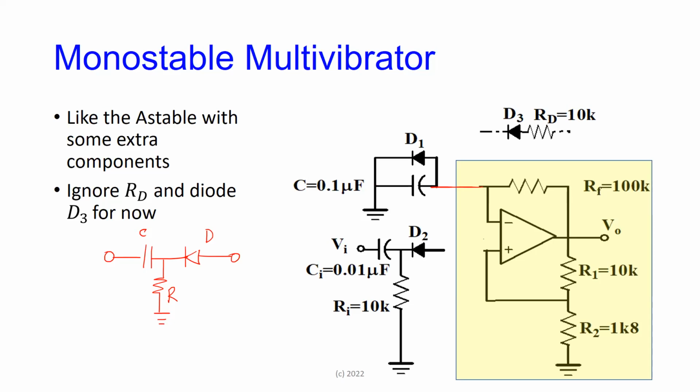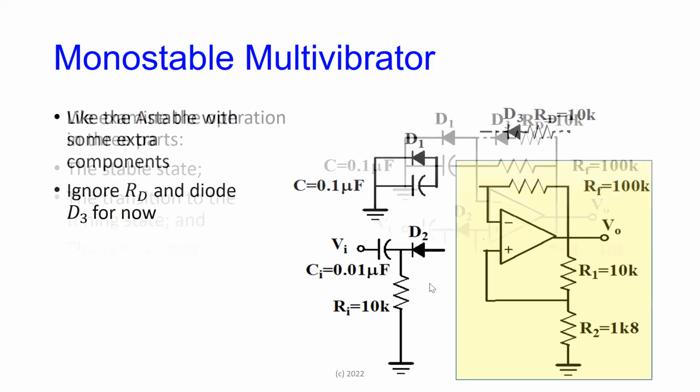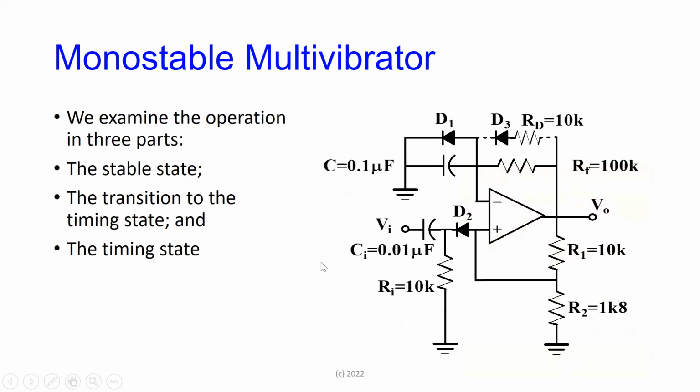What happens here now? We will get to the behavior of the circuit in a second. We saw that this circuit, without D1, is astable. So it is square waves all the time and just determined by the value of the resistor and the capacitor. Once I put these additional components in it, let's see what happens.